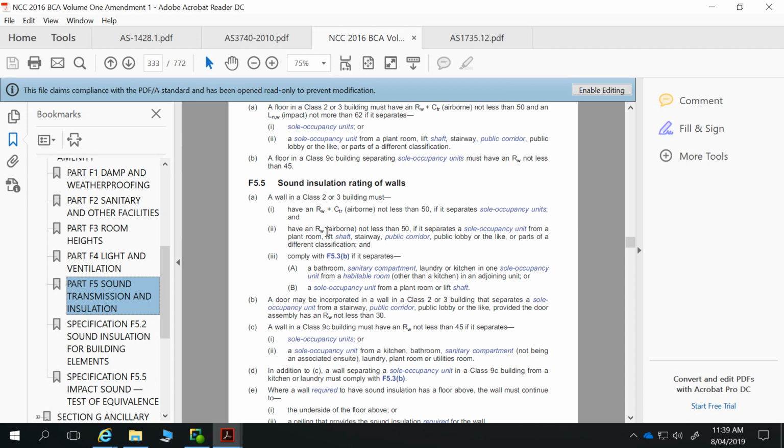Now, I'm not expecting you to design systems for that, or to work out ways of producing insulation that can have that resistance to sound transmission. All of that work has been done for you by people who supply walling products. You've got the CSR Red Book, for example, that sets out all of your fire separation walls, and you'll notice in the columns that they also show that sound transmission resistance.